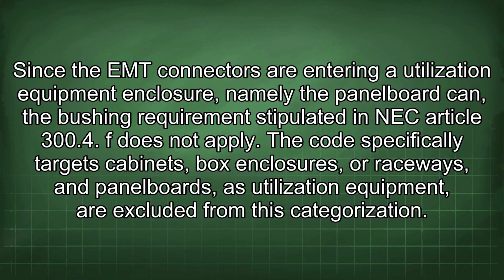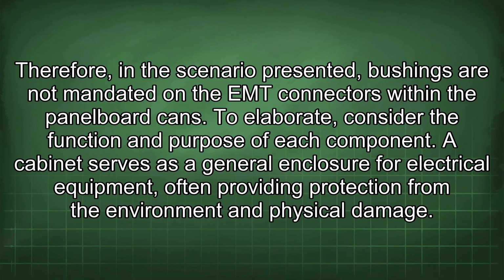Since the EMT connectors are entering a utilization equipment enclosure, namely the panelboard can, the bushing requirement stipulated in NEC Article 300.4(F) does not apply. The code specifically targets cabinets, box enclosures, or raceways, and panelboards as utilization equipment are excluded from this categorization. Therefore, in the scenario presented, bushings are not mandated on the EMT connectors within the panelboard cans.